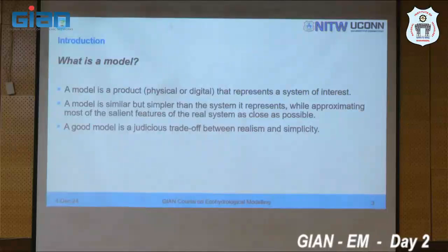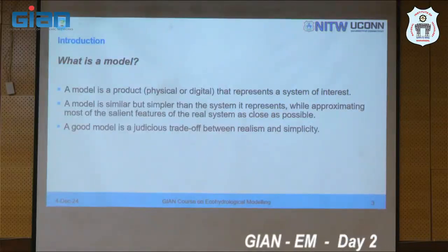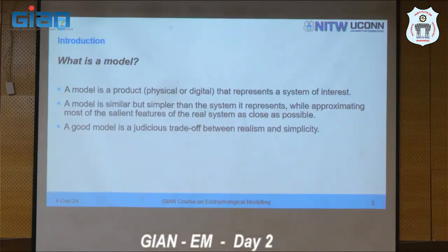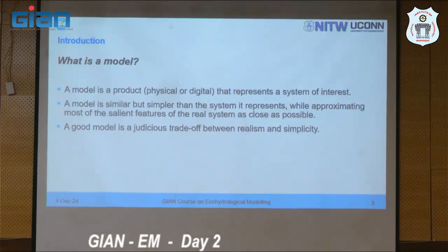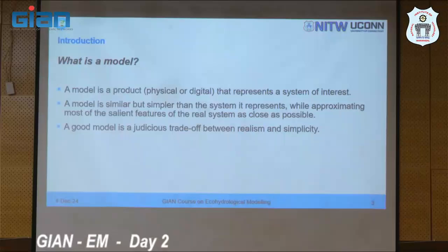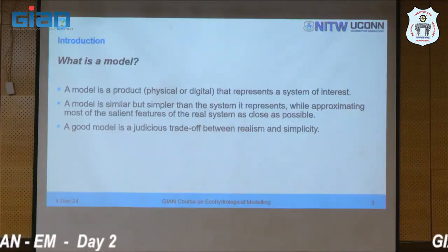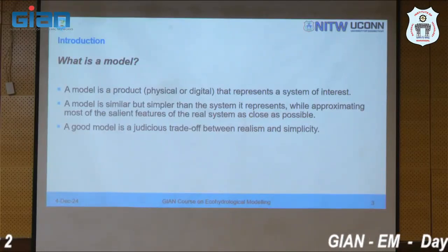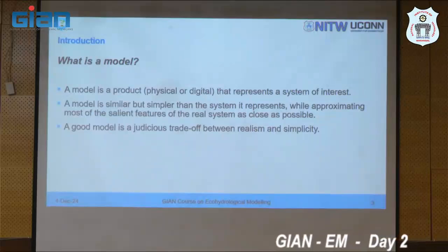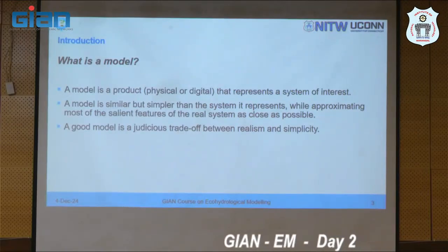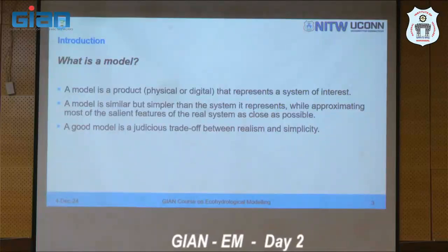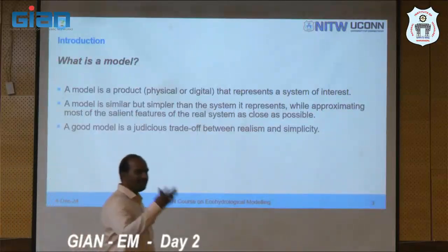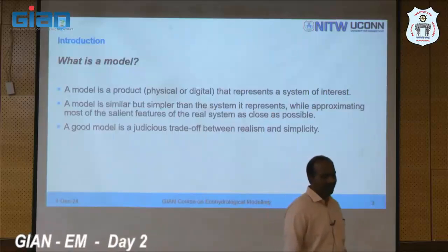So 4047 square meters, on an average we can say a 20 by 20, 20 meters by 20 meters plot. Now what is the land use map that you have? What is the resolution of that? ESRI 10 meters is the more recent one, right? But before that, 30 meters. If you take NRSC, it's 56 meters, right? Which is at a much higher resolution. And before NRSC, we used to go up to 500 meters by 500 meters.